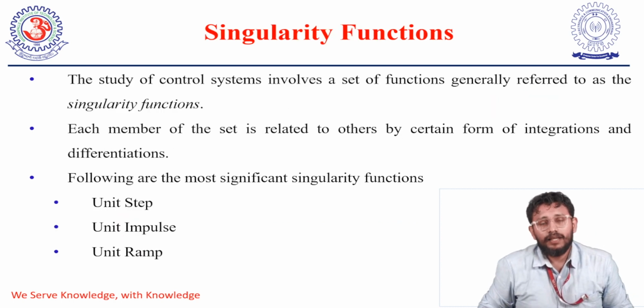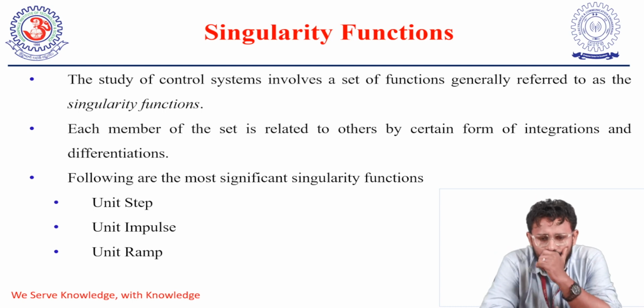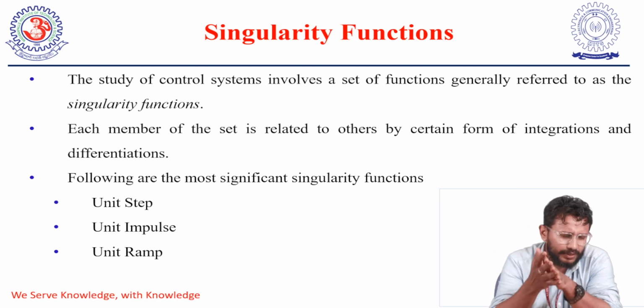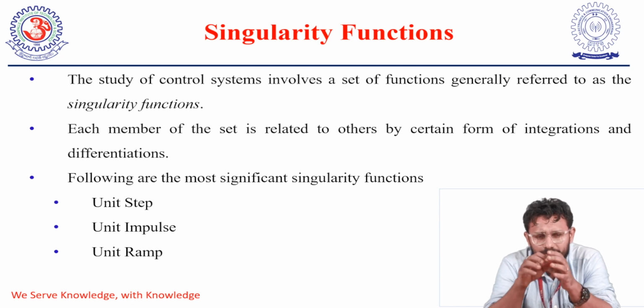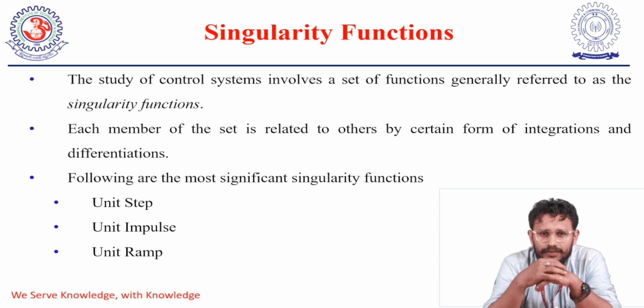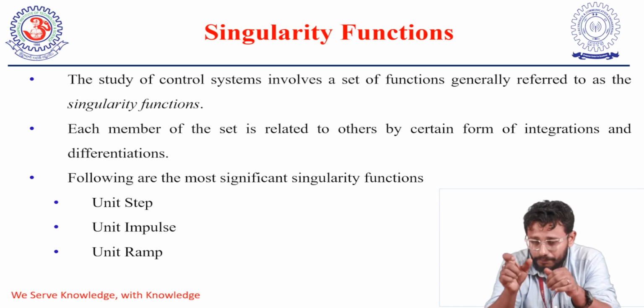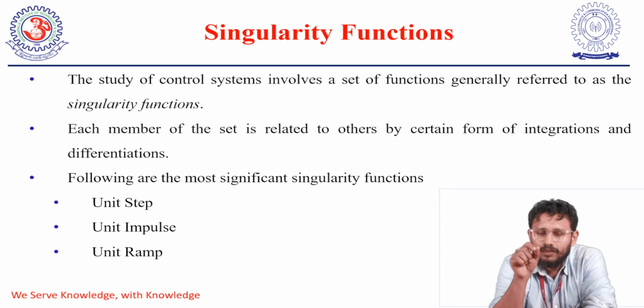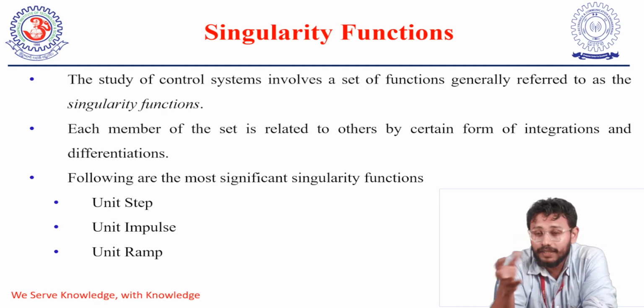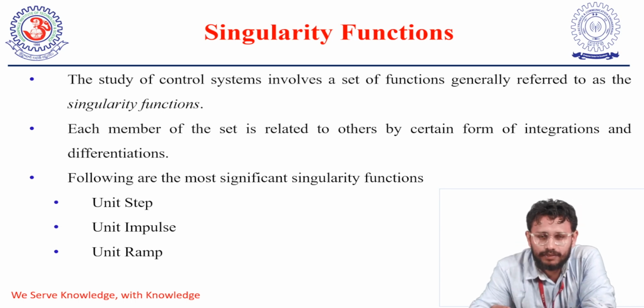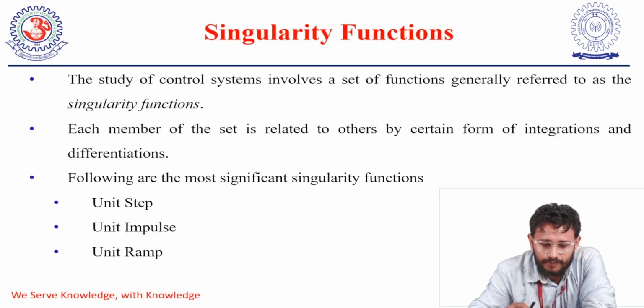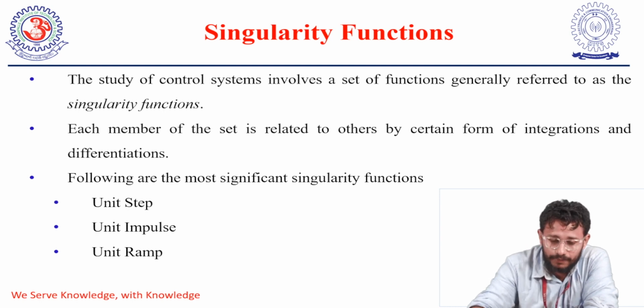Now let's come across singularity functions. The study of this subject has a special need of understanding certain singularity functions, which are a particular set of functions wherein every member of the set is related to another member by some sort of differentiation or integration. The most significant functions that you would observe in control systems are the unit step, unit impulse, and unit ramp. Let's have a look at them one by one.